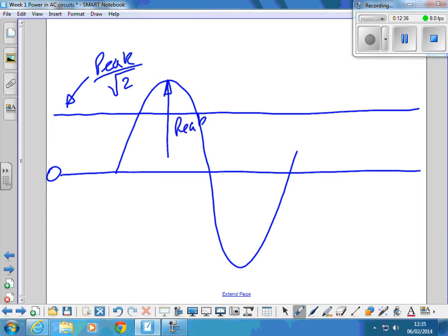To do that, you need to spend about 2 or 3 times as much money on the meter to get a true RMS meter that actually measures the RMS value and not an average converted. I'm not up to date with the current costs of instruments, but there always used to be a considerable difference. When I was in the industry, you probably had to pay £700–800 for a good quality true RMS multimeter.